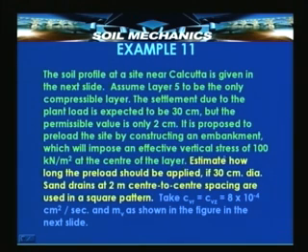Now what this means is, the size of the preload and the embankment is decided, and the stress that it will induce is also pre-decided, it is 100 kilonewton per meter square. Now the question arises, how long this preload should be kept so that it will take care of all the settlement except that 2 centimeters which is permissible.